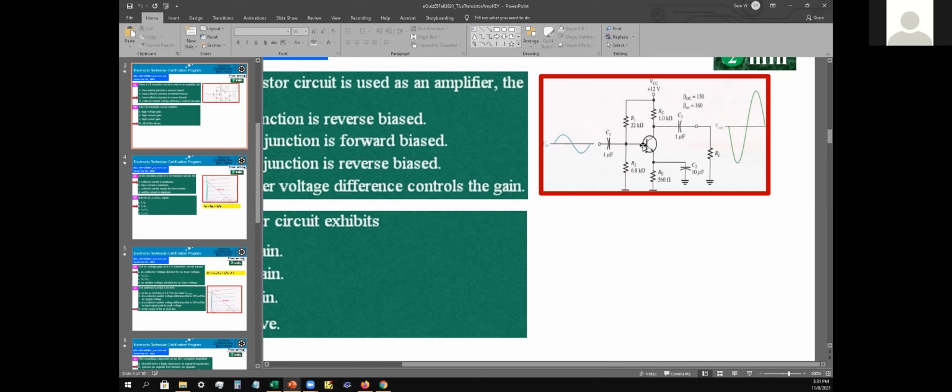So to interpret the signal on the oscilloscope, it's one straight line for DC versus AC oscillating negative to positive. You'll never see a negative DC at C3 or C1, correct? Correct, because they only go in a straight line, one way or the other. They're going to block the DC no matter what. It blocks the negative as well as the positive.